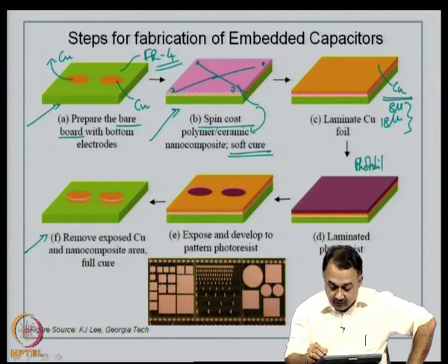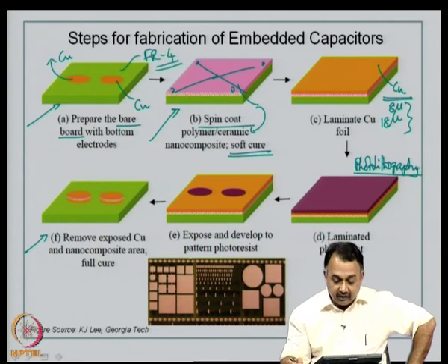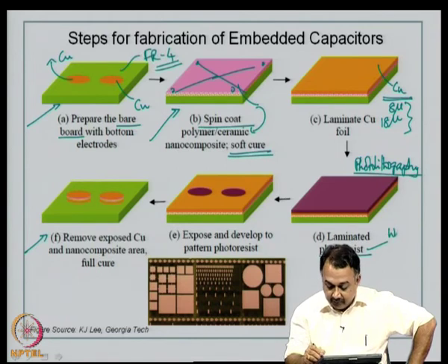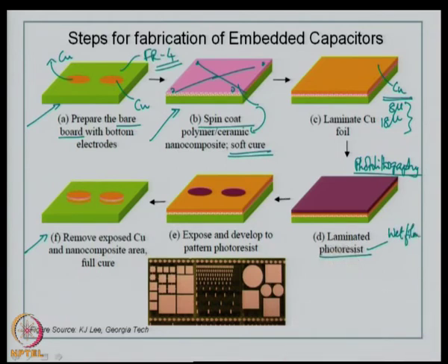which you are now familiar with in the PCB process. So, you can see that this process is highly integrated with the PWB process. So, you can laminate a photoresist, typically a wet film or a dry film photoresist material, and then this now goes for exposure to UV light using a mask. So, let me write here that a suitable mask is very important.